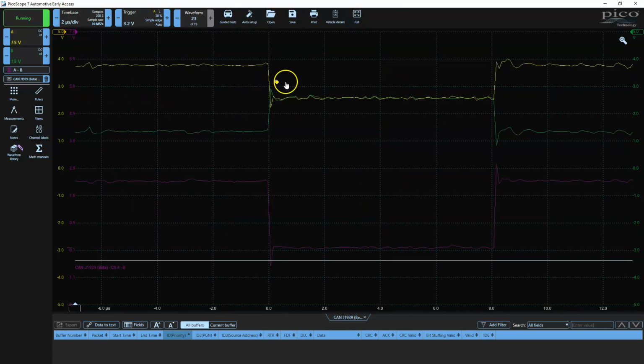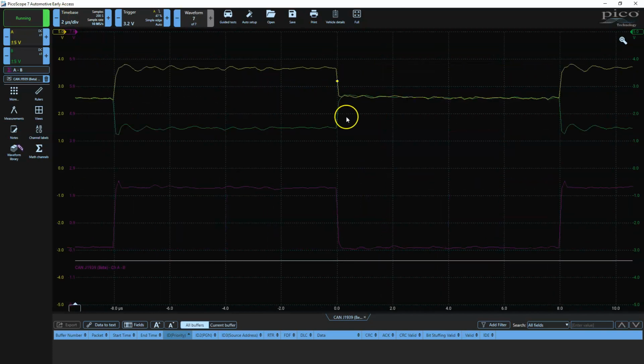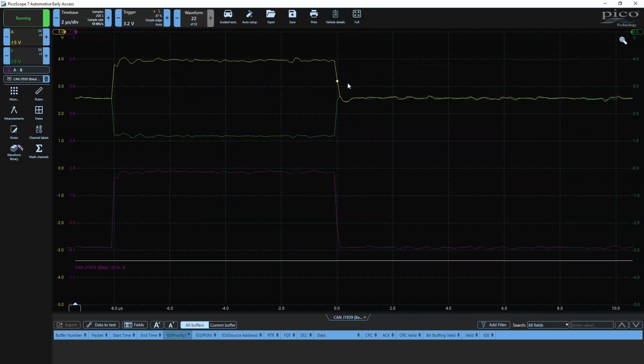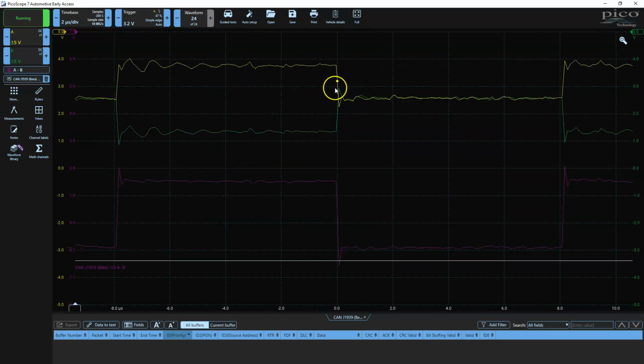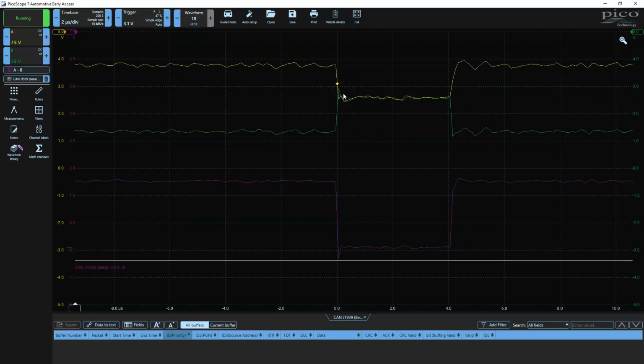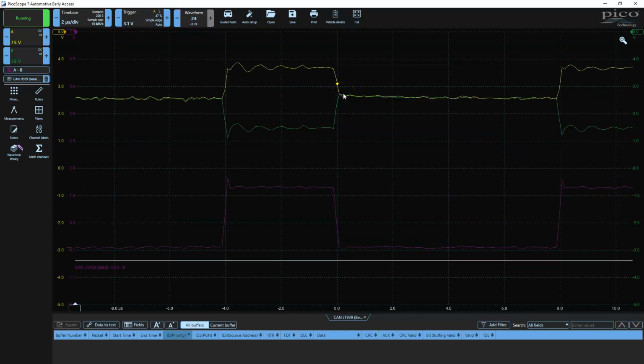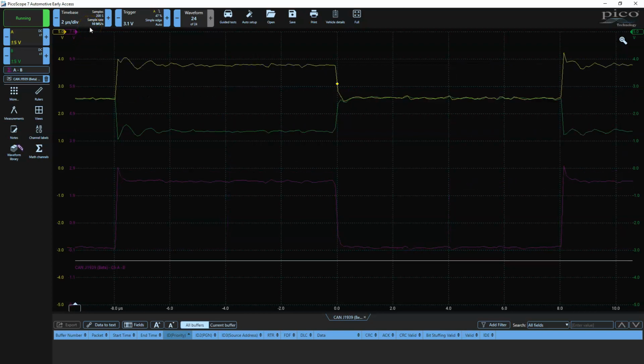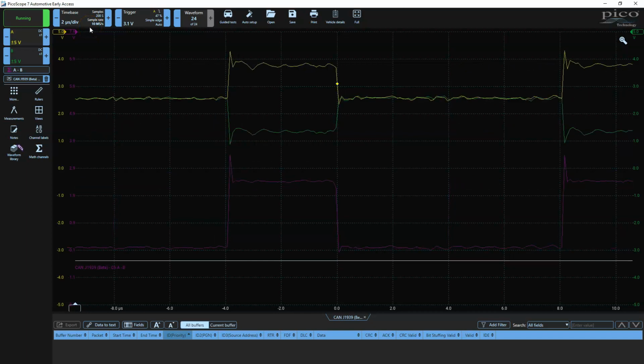I'm going to drag the trigger for this over this way. I've got it set to a falling edge trigger. If you know anything about scopes, you know that what we're looking for is when the edge of channel A drops below this value, then we're going to trigger on that. So this is pretty well damped. We can see that there's termination on this.